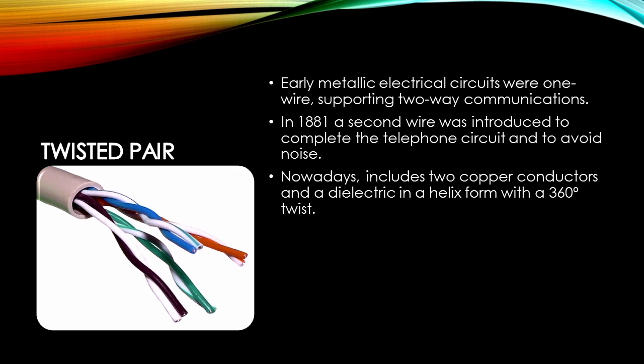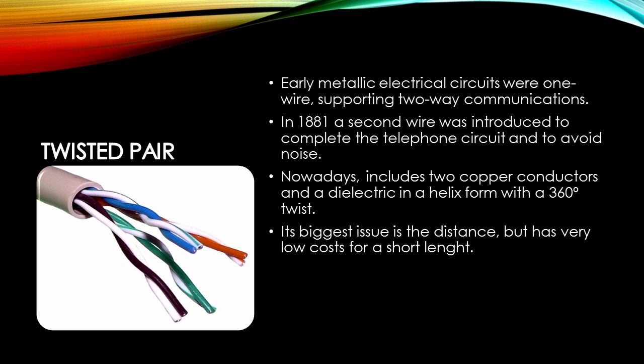The biggest issue with this twisted pair is that for some applications it involves multiple pairs, and then length can become an issue. It aggravates voice applications, and crosstalk renders data communications and other applications difficult. For this technology, bandwidth depends on several factors, including the gauge of the conductor, the frequency of the signal, the nature of the dielectric insulating material, and the length of the circuit. Twisted pair cable is especially susceptible to the impacts of outside interference as the lightly insulated wires act as antennas.